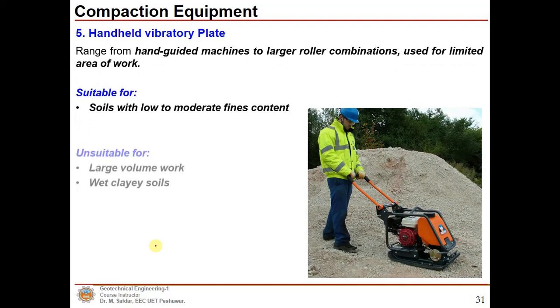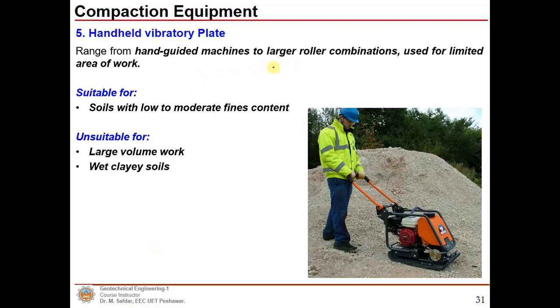Handheld vibratory plates are also used for limited area of work. So this is the important point: soils with low to moderate fines content. The suitability and the compaction is achieved for soils with low to moderate fines content, unsuitable for large volume of work and wet clay soils.